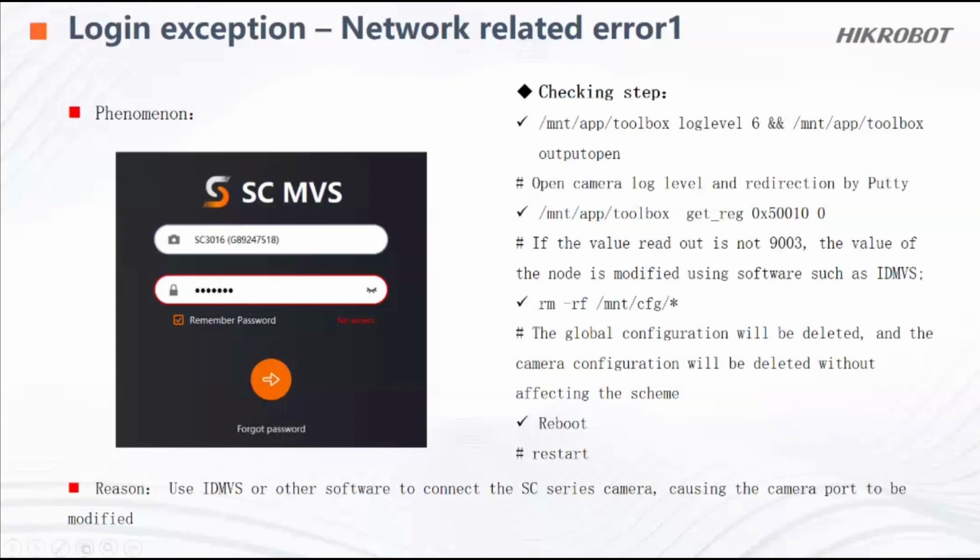And after that, even if you do not set anything here, like you change the parameter from normal to the RGB pixel format, even when you change back, you are not able to connect to the smart camera again.